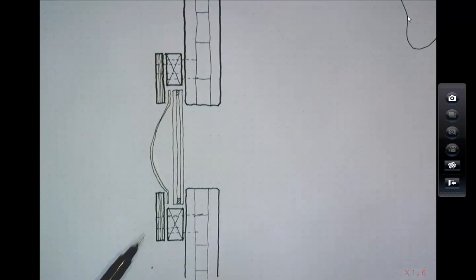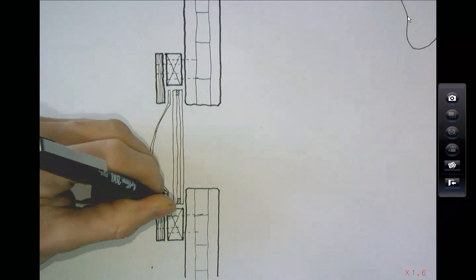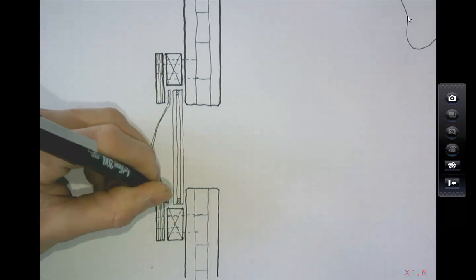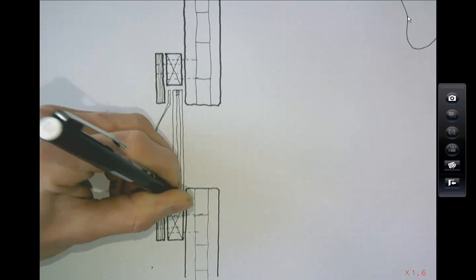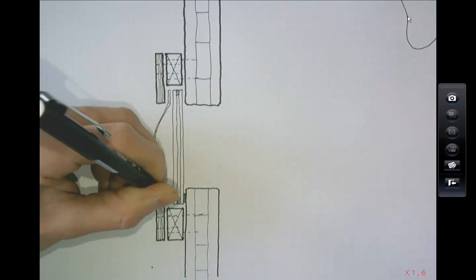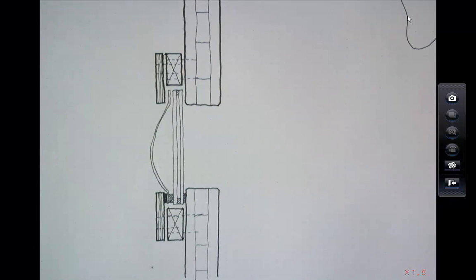Now, what you don't want is all of these different materials, plywood, plastic, glass, all pushing up against each other, because they're going to rub against each other, and if you had any variations in thermal expansion, you could get things cracking and breaking each other. So all they're doing is using neoprene strips, which are compressible rubber strips, put to clamp in between everything that's clamped together, and that allows things to move about.